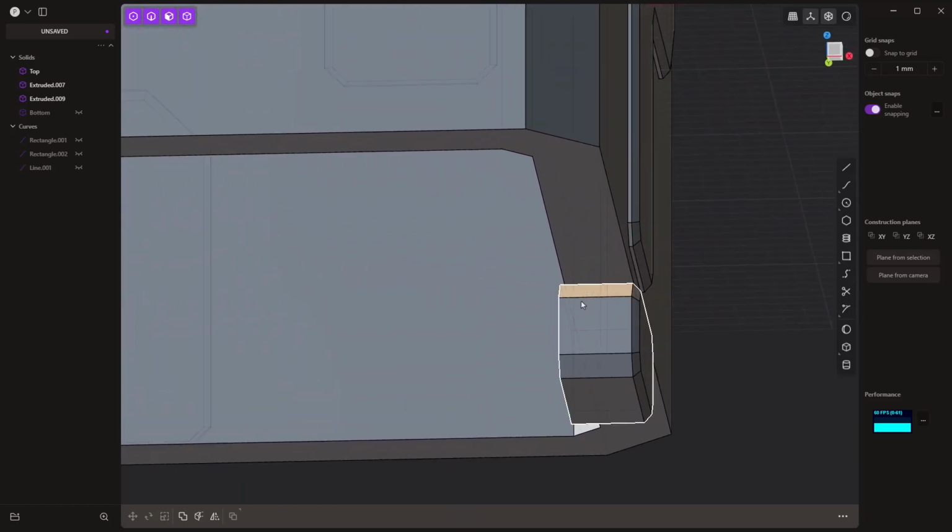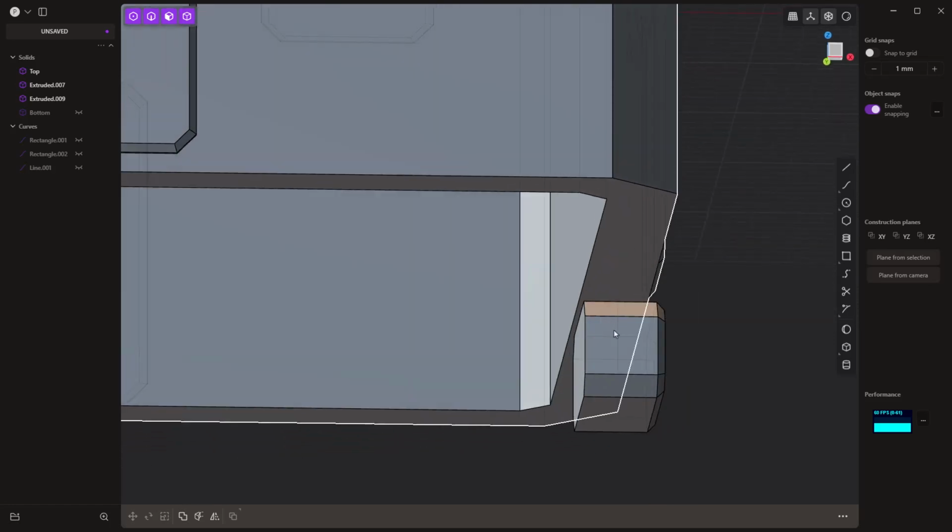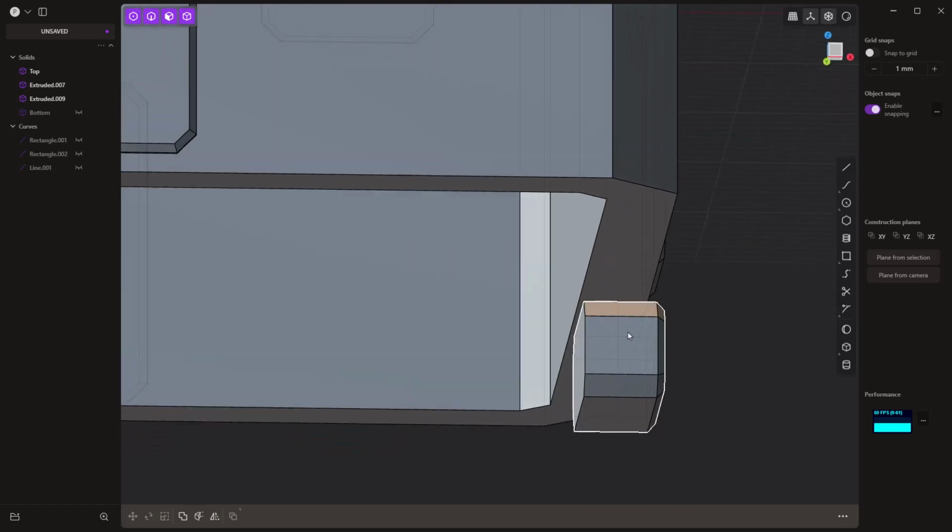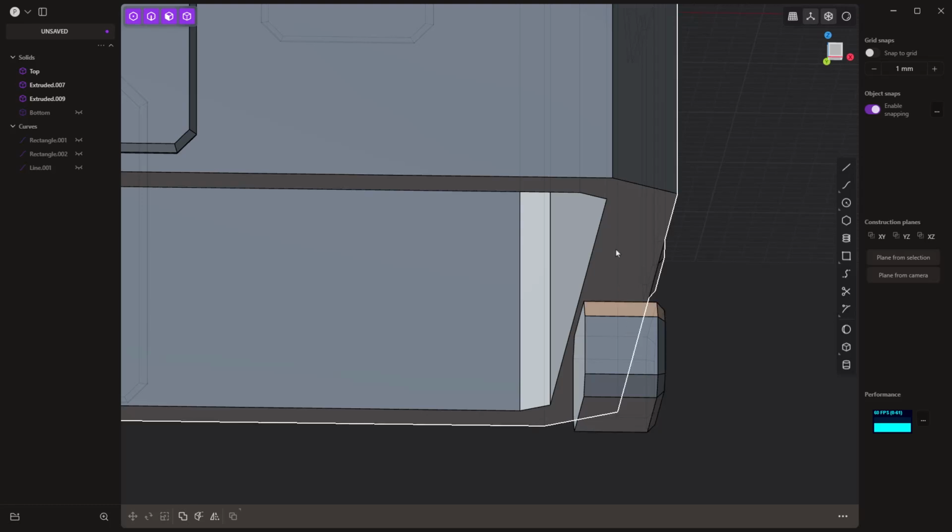One thing that we want to do is create a thin section that will allow us to flex this push button. Now, the amount that you need to actually make this happen is going to depend on your material. It's going to depend on how big the object is, obviously. But we made a 3 millimeter wall. What I'm going to do is create a 1 millimeter section, give it a little bit of gap to allow it to flex, and then join it to the bottom of the body.